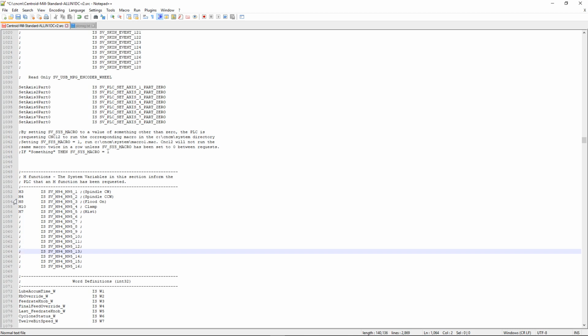The majority of times it worked, but then there was a point where the CNC software was performing, I believe, some kind of a rigid tapping cycle, and rather than issuing the M3, it was setting bit 1 of that system variable. Well, what ended up happening when they were trying to retract, I think they busted the actual tool and they scrapped the part. So with those M3, M4, M8, and M7, please leave them just as is. But anything else that you end up creating, customizing, by all means, because now you've got 128 of them.